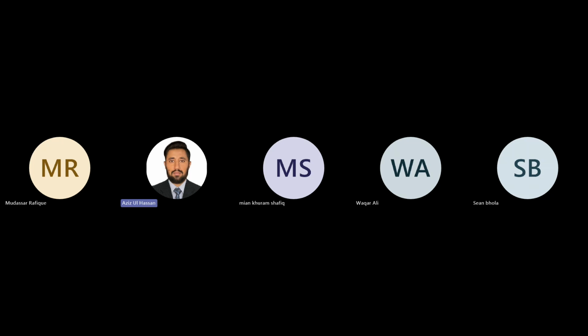because you have seen that the standard test condition of the PV module is 25 degrees. At 25 degrees, you get the maximum power. But when the temperature goes down or up, it will affect that. So when the temperature goes down, the voltage will increase.